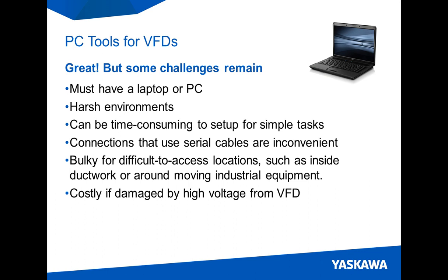Taking a laptop into difficult to access or cramped locations, such as inside ductwork or around moving equipment, can also be challenging. Making a wire connection between the laptop and the VFD could subject that laptop to damage during a power surge, for example. And at my firm, we recommend using an optically isolated USB connection between the VFD and the PC tool.